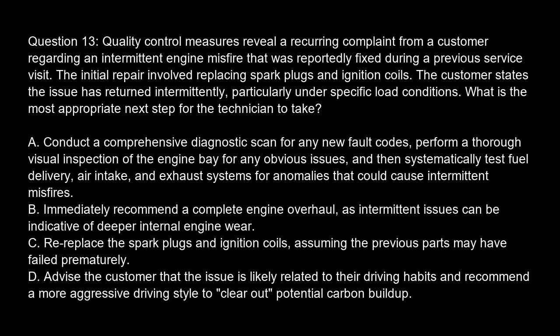Option A. Conduct a comprehensive diagnostic scan for any new fault codes, perform a thorough visual inspection of the engine bay for any obvious issues, and then systematically test fuel delivery, air intake, and exhaust systems for anomalies that could cause intermittent misfires. Option B. Immediately recommend a complete engine overhaul, as intermittent issues can be indicative of deeper internal engine wear. Option C. Re-replace the spark plugs and ignition coils, assuming the previous parts may have failed prematurely. Option D. Advise the customer that the issue is likely related to their driving habits and recommend a more aggressive driving style to clear out potential carbon buildup.